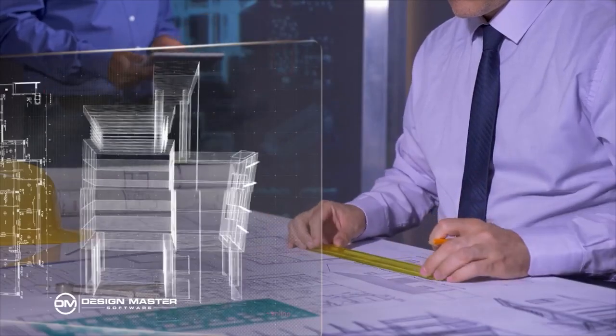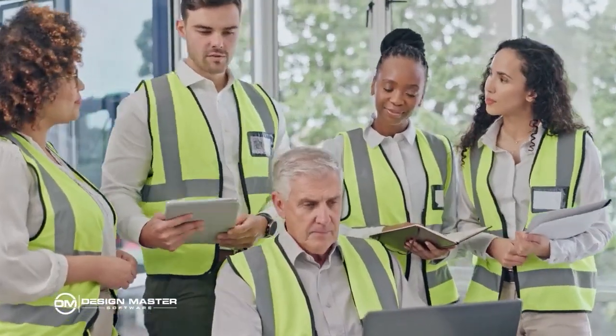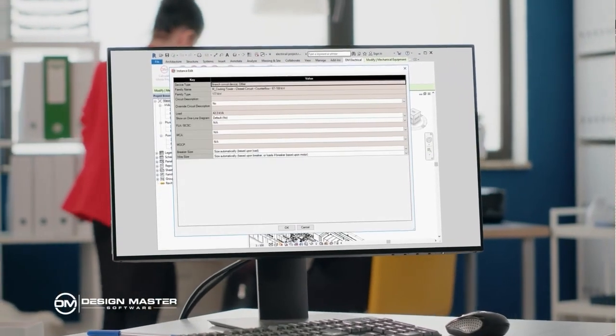Using BIM, that constraint goes away because in BIM, you are placing your motors. You're specifying your load. You're specifying what they're connected to. All of that information is being created because you have to put those pieces in. You have to get them connected. The feeder and service load calcs are going to depend on knowing that that's a motor because you do some diversity and you do demand factors based upon the fact that it's a motor. So you need to know that it's a motor.